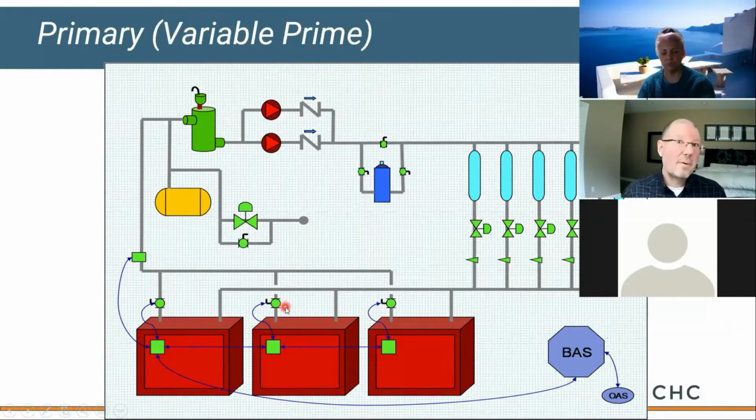Well, if you've got a flow schematic, that would help us. Most chillers are still gonna use motorized valves. Do you know how they're being isolated at this point? They do have flow through both of them, motorized valves. Okay. And in the past when I had a series of chillers that would come on together, I used primary, secondary, but in this case we were hoping that one chiller would be enough for the load and they would just have a redundant chiller.